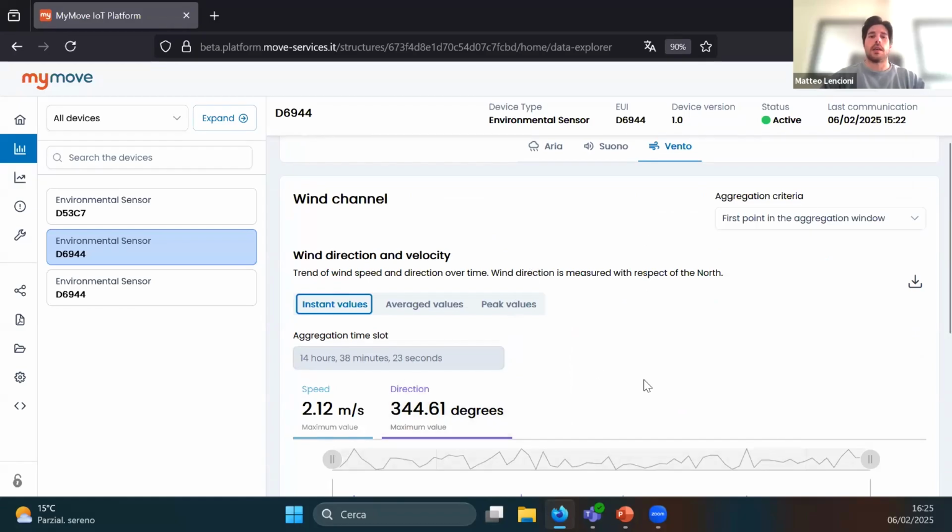So you'll be able to see the typical windrose with all the sectors for the wind direction and the wind speed categories, where you can select maybe a Beaufort wind velocity scale and maybe a 16 wind direction sector, and then you can build that windrose that statistically shows you the percentage of the time that the wind was blowing from a certain direction and in a specific wind speed category.